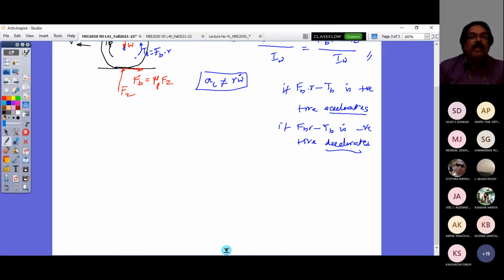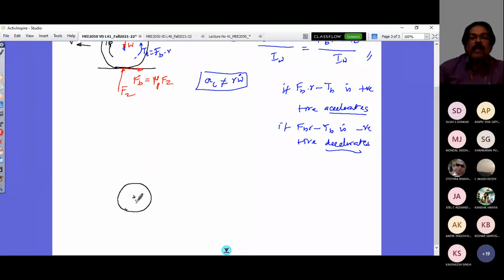So when I say that, my circuit goes like this. If this is my wheel, I would have a pickup electromagnetic sensor here, somewhere, and there would be a toothed wheel attached to this rolling one. So this pickup would send a signal some 90 to 100 times per revolution, and it would pick up the speed of your wheel. This speed would be sent to a control unit called the electronic control unit.